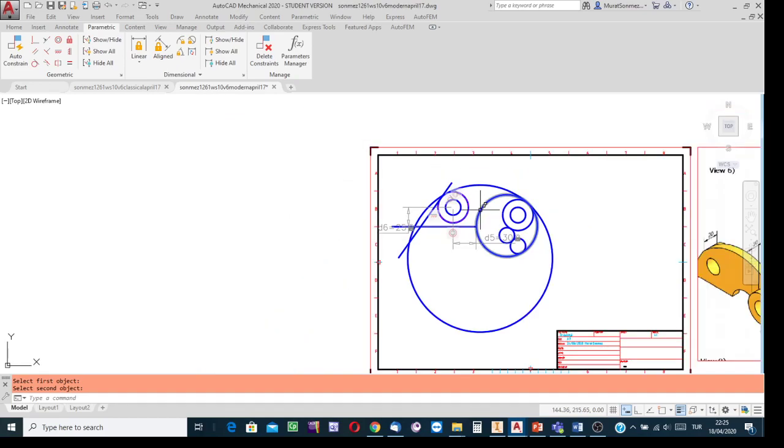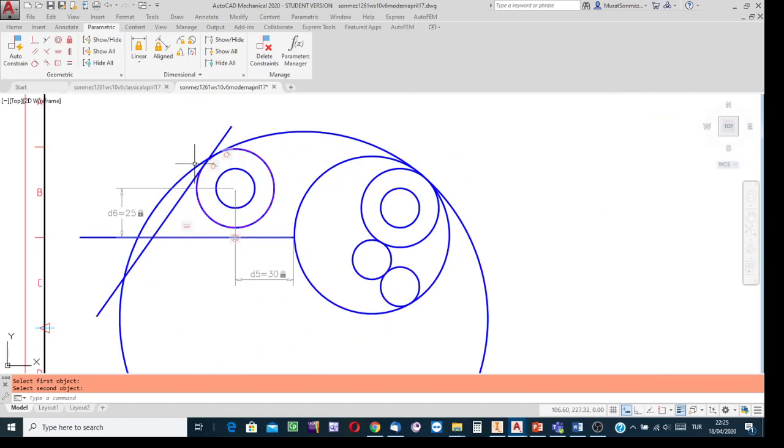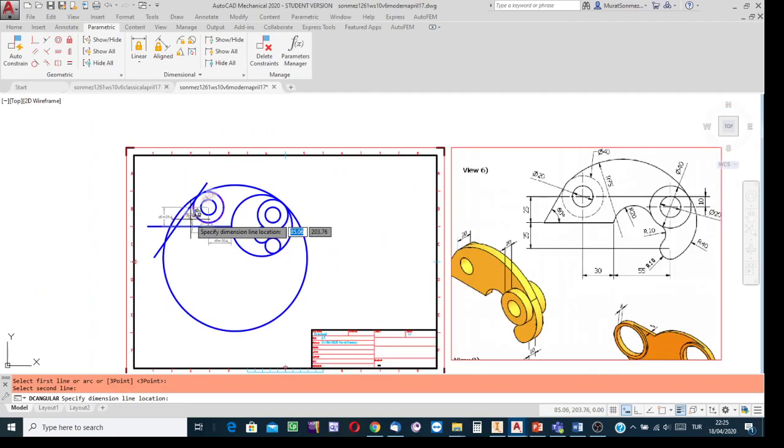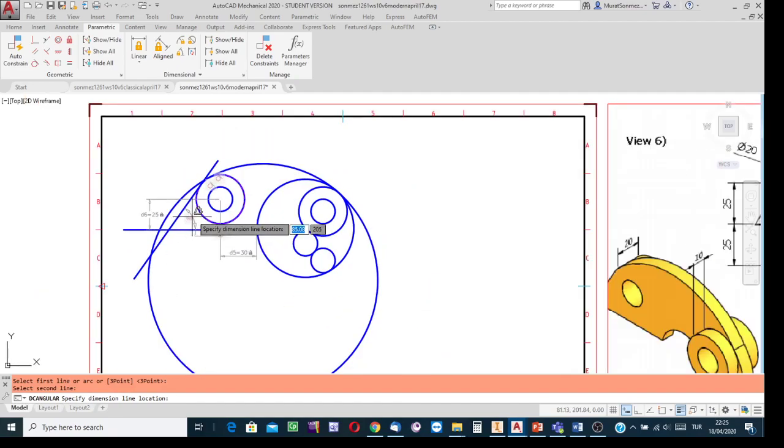The other constraint is the inclination angle. In the classical method, you need to calculate the angle with respect to the line which passes through the tangent point in the counterclockwise direction. But in the modern method, directly input the angle. Click on the angle inputting button, then indicate this boundary line as the reference and indicate this line, and move the cursor to have the angle as measured in the same sense. Click, and after the click, in the box, write the angle 60. That is it. Now you see this line as it is required. Perfect, correct.